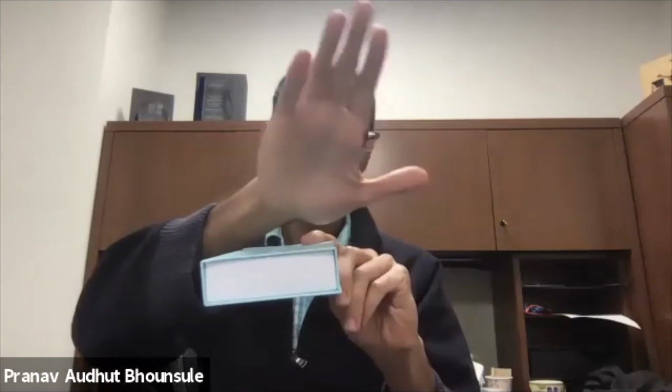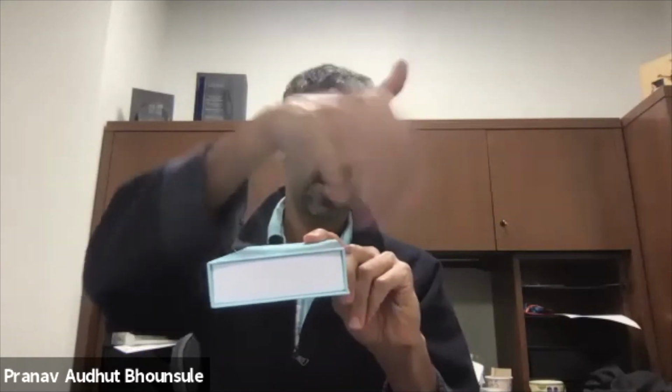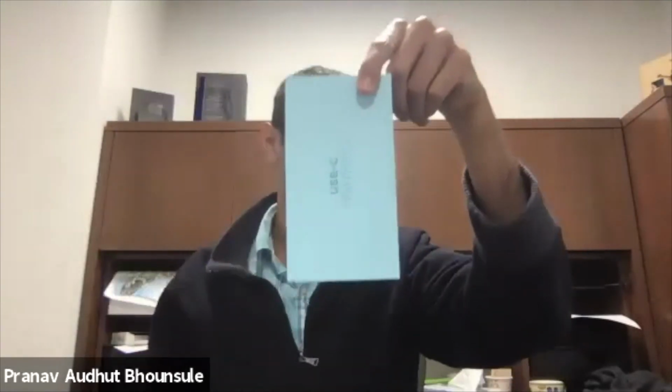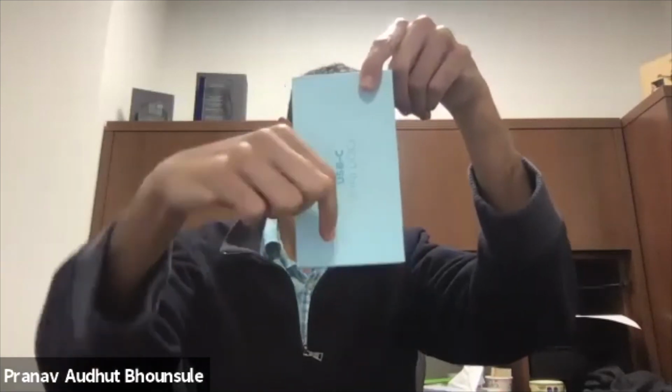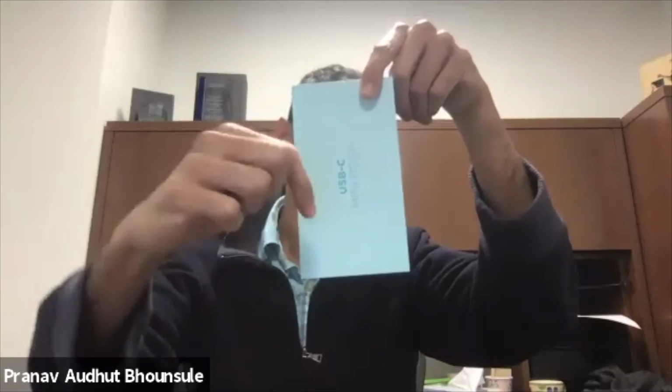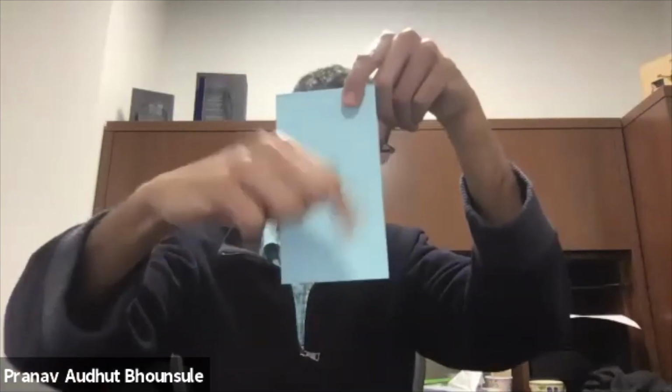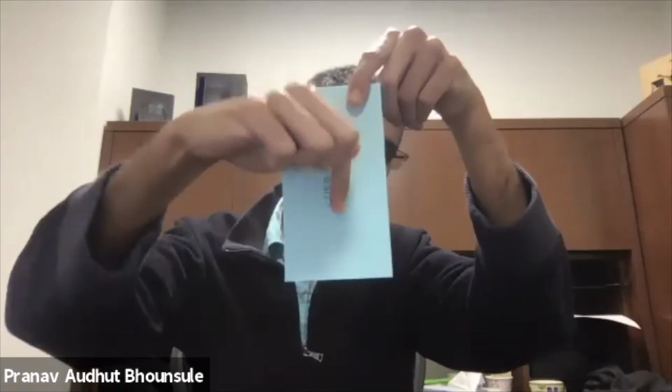Now let's try to switch the order. Okay, again, z is up, x is there, y is there. Let's try to rotate about the y-axis first. So y-axis is there. Curl my fingers along the direction of rotation. So it goes this way. That's the first rotation. Now z is pointing towards you. Y is still this way because I rotated about that, so it doesn't change. And the x-axis is down.